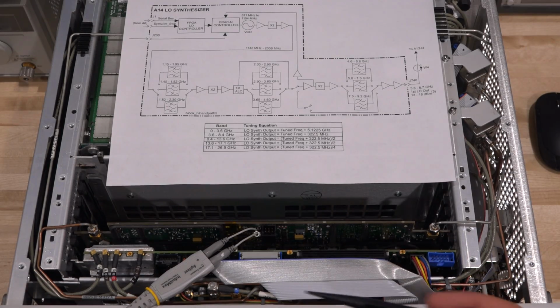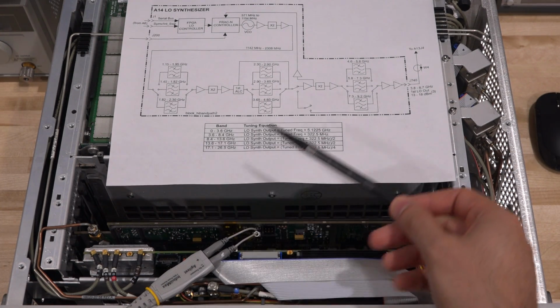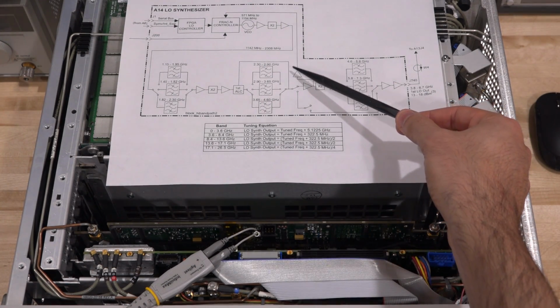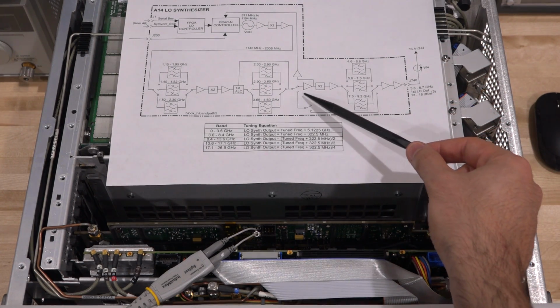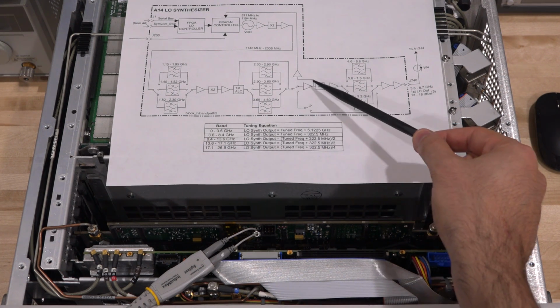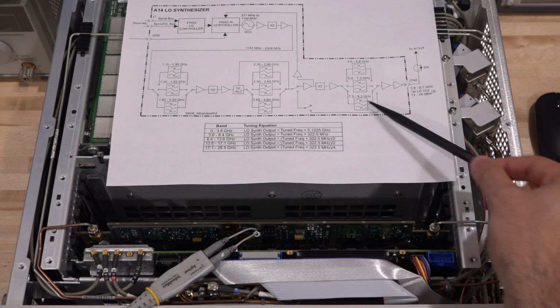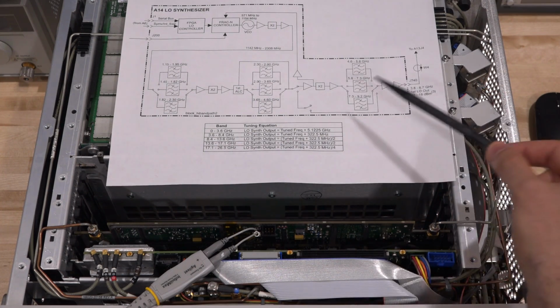Okay, so here's our connection to our active probe over here, and just to remind you, we are measuring this signal right here, right before it goes back. By the way, there's something wrong in this diagram. This switch is in the wrong place. This signal cannot be taken after the switch. It has to be taken before the switch, because otherwise when you switch this path, you simply won't have any feedback. So the diagram is wrong. But anyway, it doesn't matter.